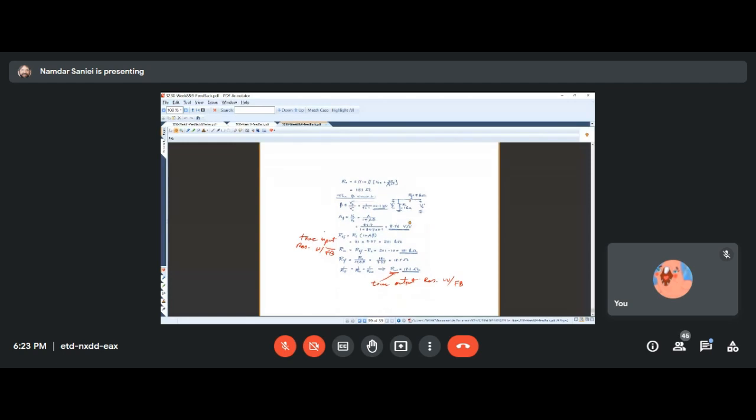And then we also found beta, put it together with the amplifier gain, found the gain with feedback, input resistance under feedback, multiplied by 1 plus A beta, and for output with feedback, divided by 1 plus A beta, took the RS and RL out, then we had true output resistance with feedback and true input resistance with feedback.